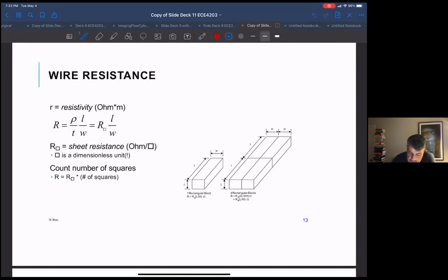Like when I was just talking about the numbers for the 0.18 micron TSMC process, the C sub G was given as 1.67 femtofarads per micron. Again, they just cut out the extra dimension and assumed that your length was 0.18. Designers are constantly trying to do that, so they only keep track of a few numbers, because of the complexity of what they're trying to design. They're constantly trying to simplify because they have a lot of individual components to deal with.